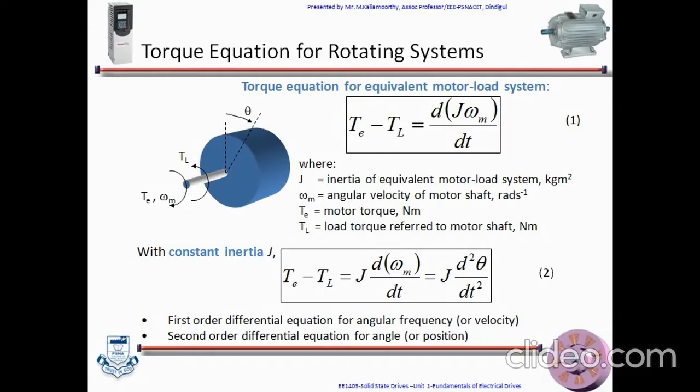Drive accelerates or decelerates depending on whether T is greater than or less than TL, that is whether TE is greater than or less than TL. During acceleration, the motor should supply not only the load torque but an additional torque component J d omega by dt in order to overcome the drive inertia.